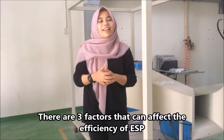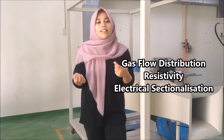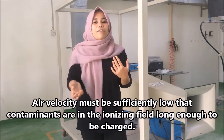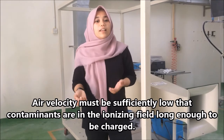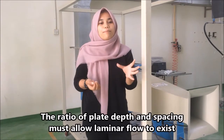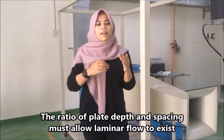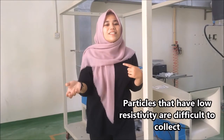Three factors that can affect the efficiency of ESP are gas flow distribution, resistivity, and electrical sectionalization. For gas flow distribution, the air velocity must be sufficiently low that contaminants are in the ionizing field long enough to be charged. As for resistivity, the ratio of plate depth and spacing must allow laminar flow to exist between the plates. Particles that have low resistivity are difficult to collect since they are easily charged and will lose their charge on arrival at the collection electrode.